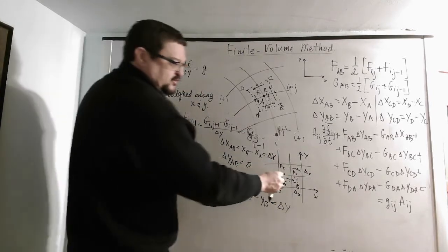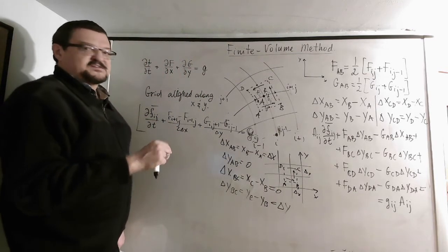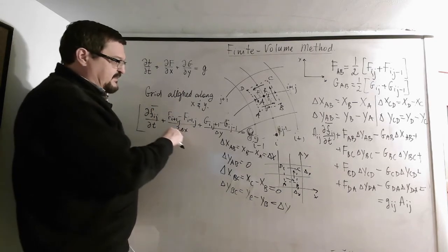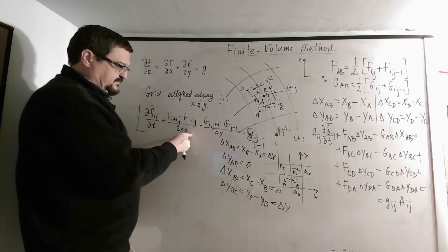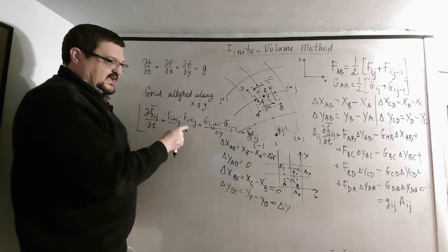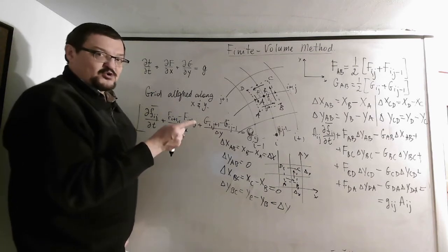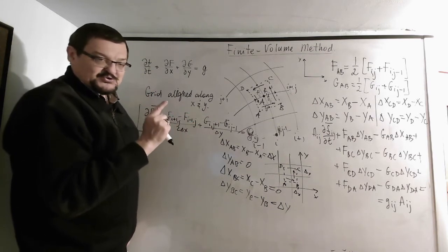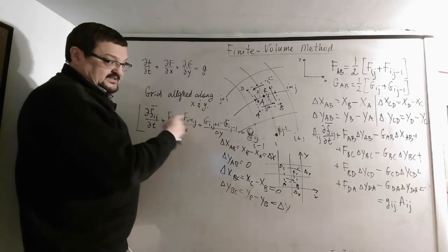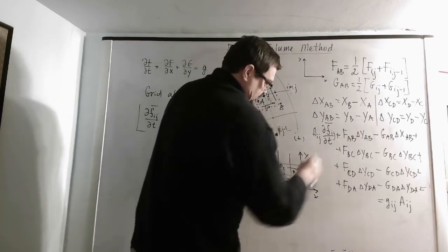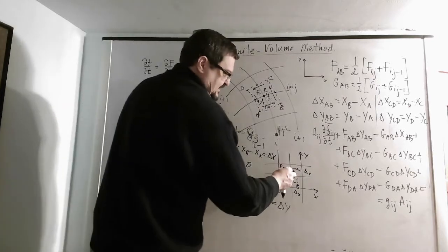So basically, in order to use this scheme, we need to use a similar stability criterion applied for local grid spacings as before. For example, if we use a certain scheme, like say the leapfrog scheme for this time derivative, and here it would just be central differences, it would be stable in one dimension for Courant number smaller than 1. For 2 dimensions, it would be the Courant number divided by square root of 2. Remember that when we talked about stability in 2 and 3 dimensions. So we would then apply it locally.